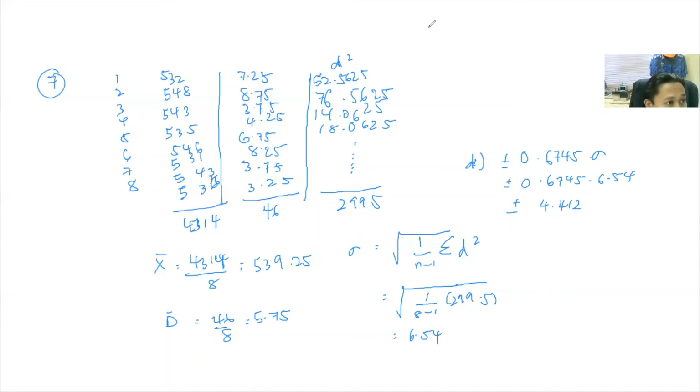Okay, I explain question number 9. So 1% of the tolerance, with the range from 0 to 150. As we know, 1 per 100, that is 1 percent, multiplied by the full scale of 150, so the answer will be 1.5 volts.